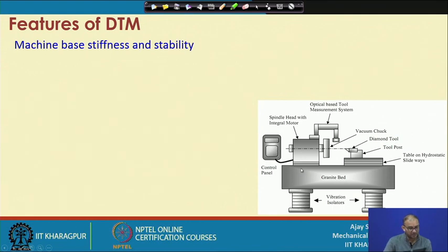Everything is required here also, and the requirement is even more stringent, because our depth of cut is in ones of microns only, although you can give more depth of cut in tens of microns. This process demands even more than what is required on a micro machining machine. So machine stability and stiffness are mostly repeated, similar to what we discussed for the micro machining machine components.